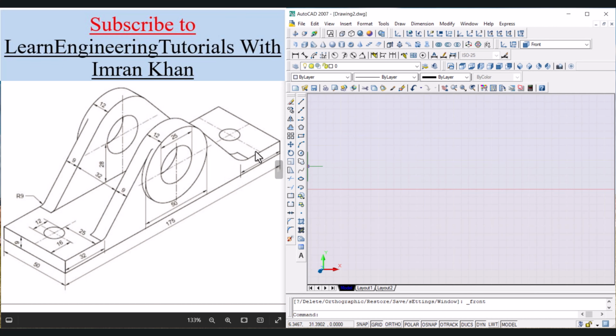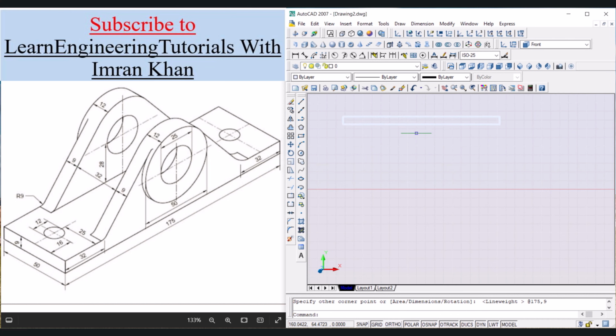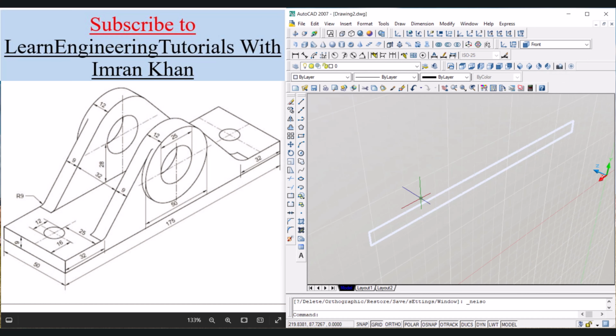First we will draw this rectangle and then we will extrude it to give it the width of 50 mm. So click on rectangle, click over here. Now turn on LWT. This way give the dimensions as 175 tab 9. Enter. Now visualize this object in the northeast isometric view. So in this view we can see this object now.